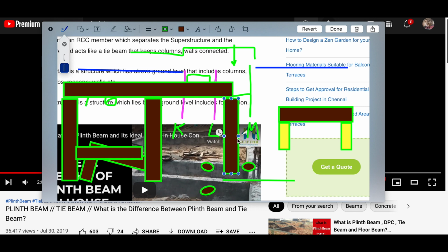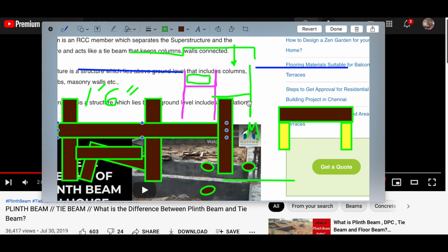And this is KLM, let's call it. Up here, and when this one goes away, well, this out here, the parking garage one, is still the same height, the 1310. That's already designed to be freestanding, and it's turned, and actually this is turned, I believe, this way. So that's already freestanding, needs to turn more square. So there is no lateral bracing for it. It's designed to stand strong like a tree, right? Like a post. It can do that.